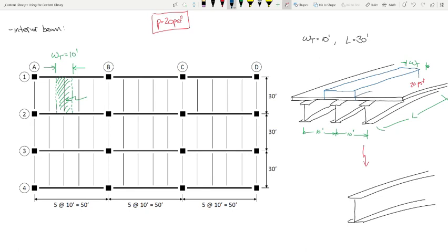It's seeing this pressure of 20 PSF act on top of the beam. Now what I'm going to do is distribute that to this beam so that the beam is seeing just a distributed load. Now how am I going to do that? I have a pressure load of 20 PSF and it is applied over a width of 10 feet.